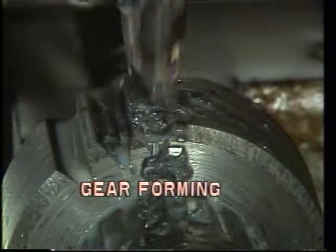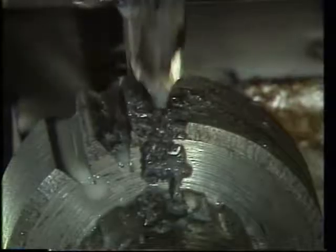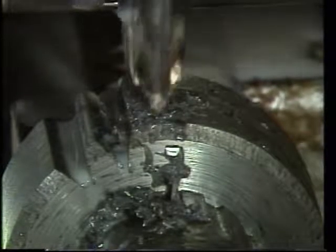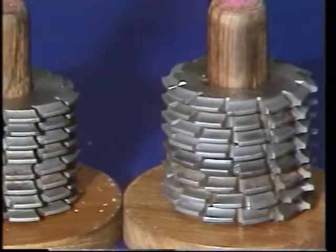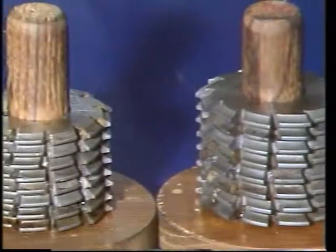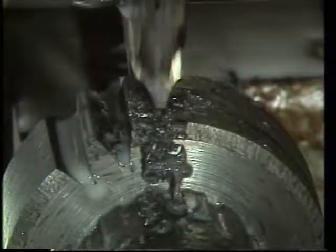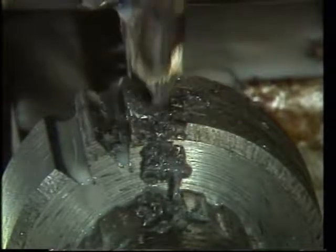In the form milling process, the cutter has a profile similar to the form of the tooth space. The tooth space is a copy of the cutter. A wide range of cutters is required for gears of different numbers of teeth with different base circles. Hence, in practice, each module range includes a set of 8 standard cutters, producing an average result which is a fair approximation to the ideal.